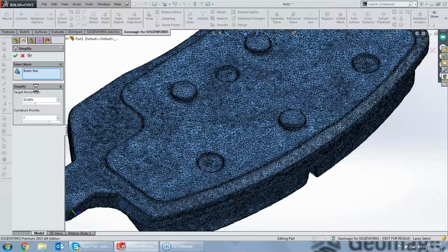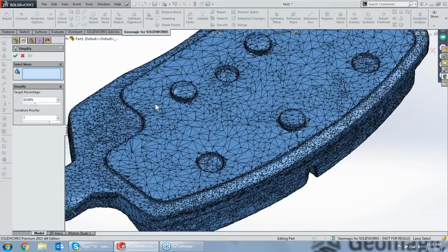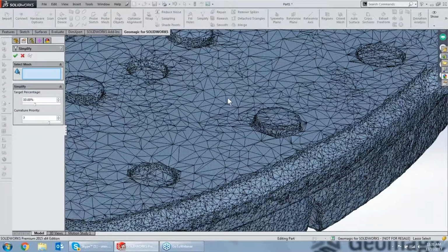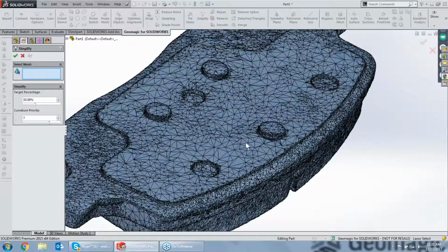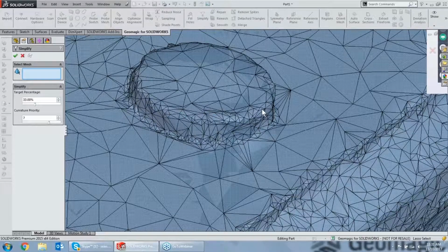And we'll do a curvature-based intelligent decimation. Or, for those of you that don't want to have such a mouthful of a term, basically, a smart simplify tool, where I make larger triangles in the areas that I have flatter curvature on my scan data and still smaller triangles to convey the high level of detail that the sharper corners have here.